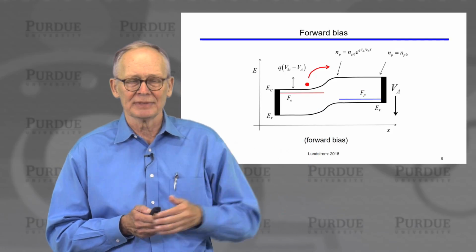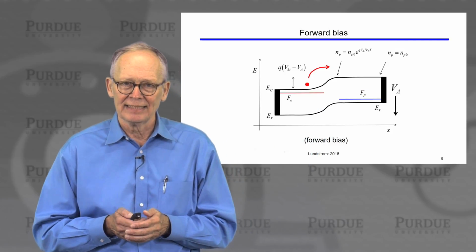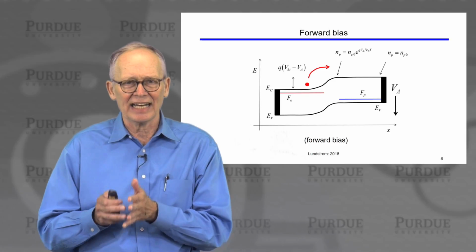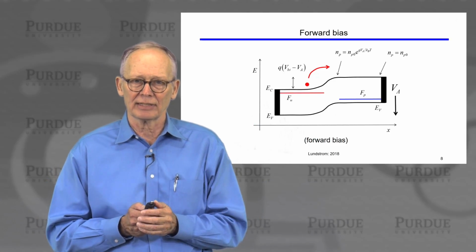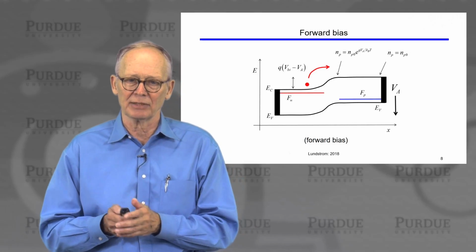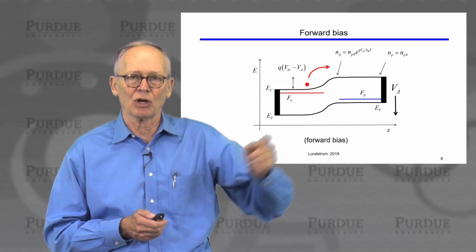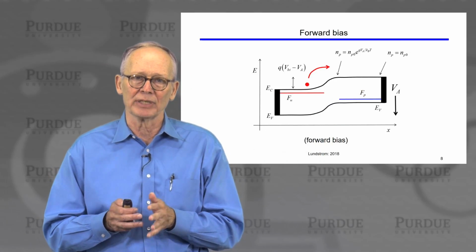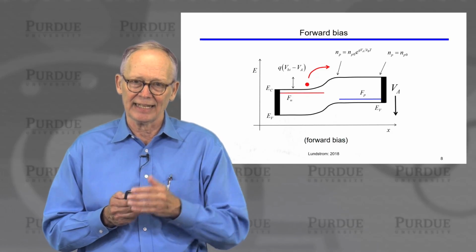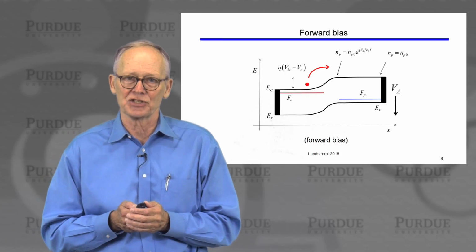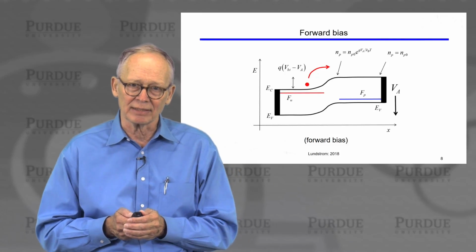And we will assume that the ohmic contact has a property where it's a highly defective surface. Any minority carrier electron that reaches that surface immediately recombines. So we will always maintain the equilibrium concentration there. We can't get away from equilibrium because the excess electrons that have been injected recombine immediately when they hit that metal contact.